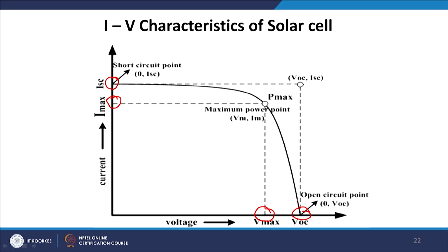Now, to operate these solar cells, they have to operate at a particular point. When we operate these solar cells at a point like P, we get maximum current and maximum voltage. So, at this point P max, I max times V max gives the maximum power, but very often we do not get the maximum power. What we get is a more realistic case, which is not this point but this point, and this point is actually the area under this rectangle.